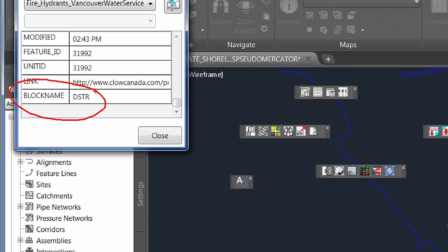So if you add a block name type as well as rotation and other properties such as block attributes into your GIS database and control them accordingly, then you can use that to drive out AutoCAD features from your GIS database, which is very different than what we're used to when we're using FDO data sources, and we'll contrast it when we get there. But when you use an FDO data source, you're not creating a true block necessarily. You're using a symbol of a block that then you can create a block out of, but here you're driving the block directly out of the database.